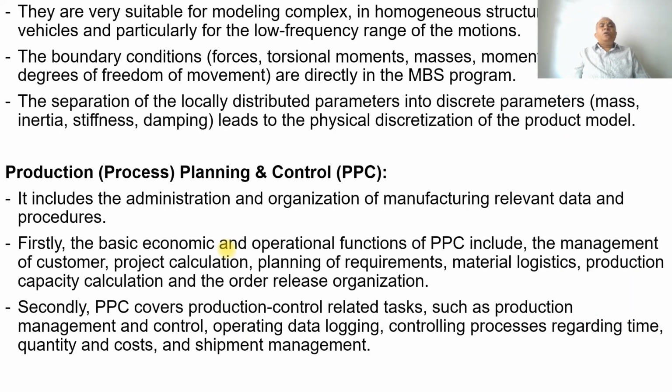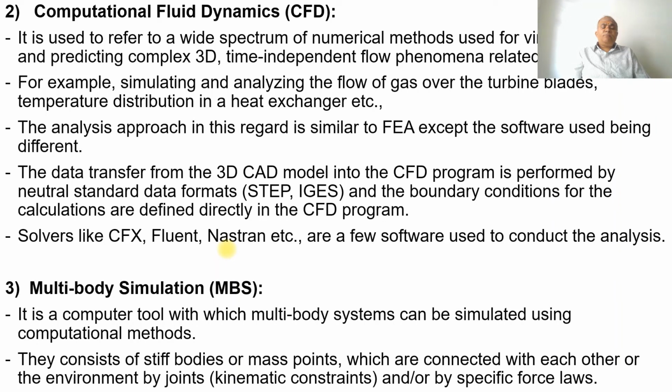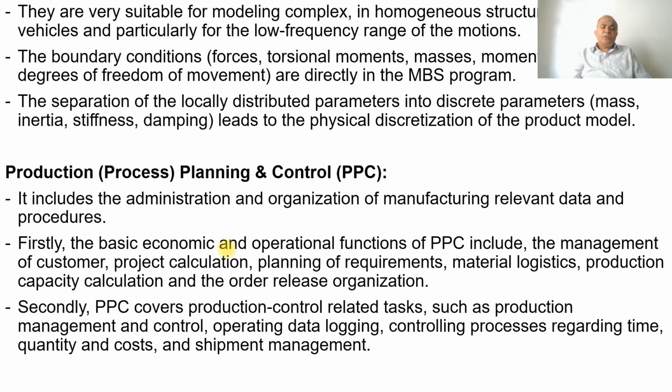They are very suitable for modeling complex inhomogeneous structures such as full vehicles, and particularly for the low frequency range of the motions. Boundary conditions such as force, torsional moments, masses, moment of inertia and degrees of freedom of movement are directly applied using the MBS program.